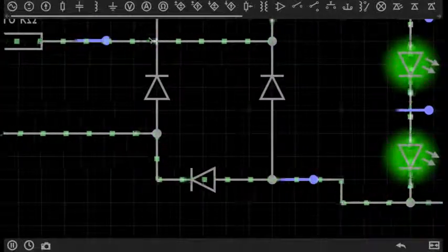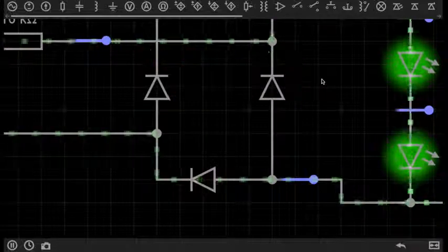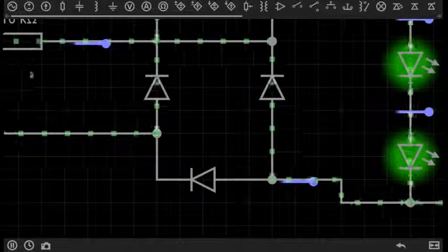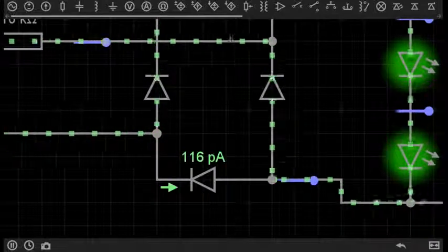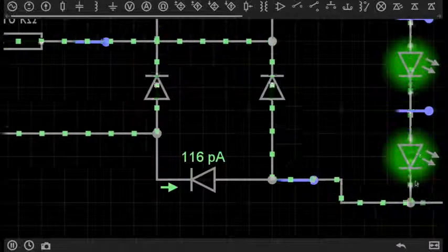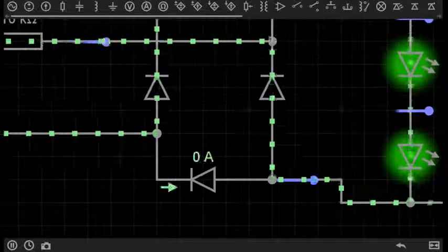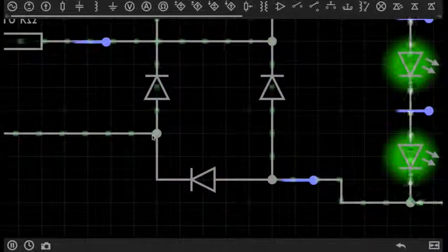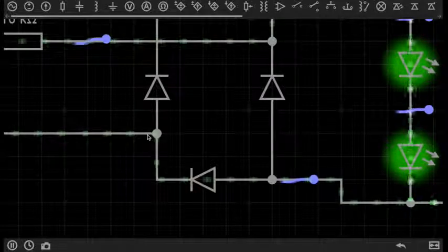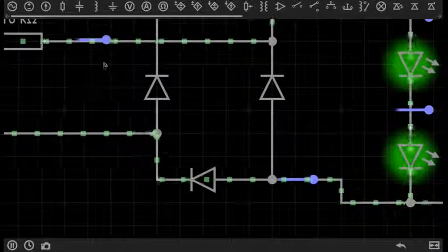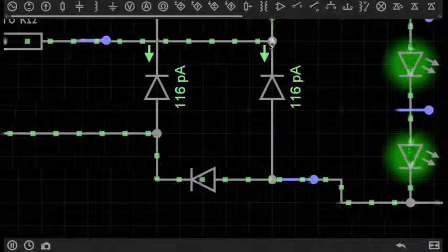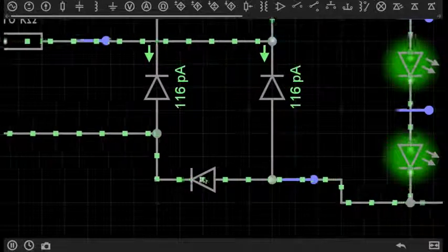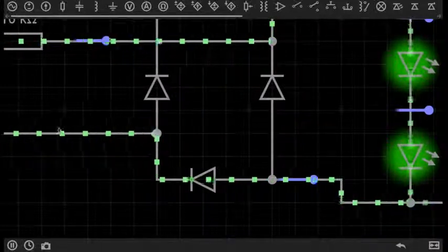So we've followed it from this side, and there are another 2 diodes to obviously complete the circuit, which means that when current flows backwards this way, it goes all the way up here, round to the LEDs, through the LEDs, and back through this diode and back to the AC power supply. And when the current starts to flip the other way, you can see it goes in this direction all the way up here through the LEDs and returns to the AC power supply in this direction.